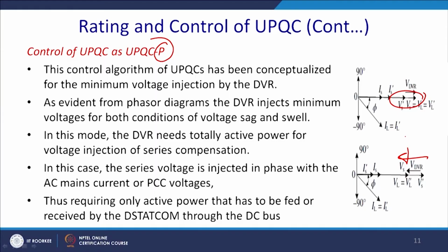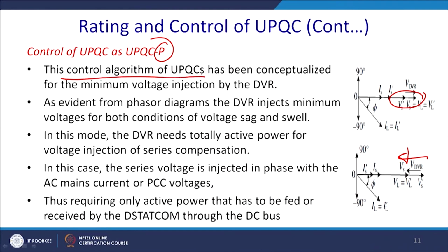Essentially, it is a sag and swell compensator. We shall discuss all the control techniques. Thereafter, we shall discuss the block diagram of UPQC. This control algorithm of UPQC has been conceptualized for minimum voltage injection by the DVR.